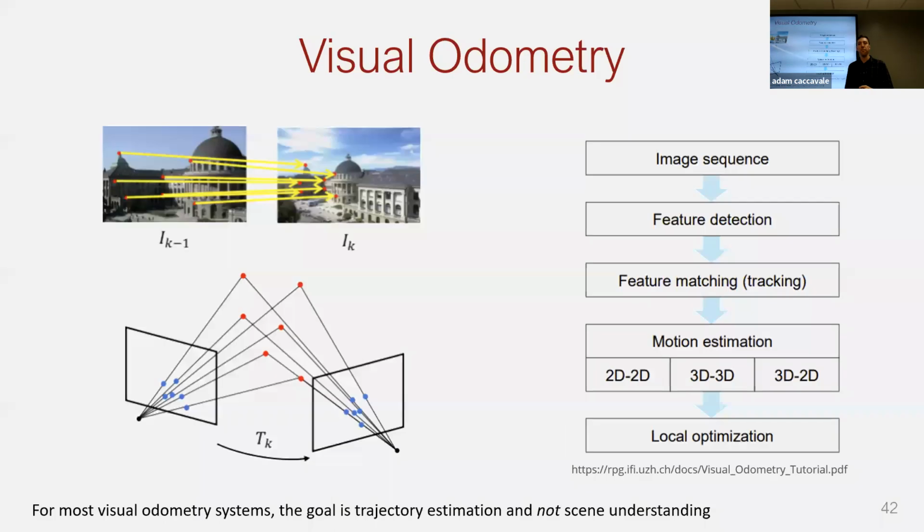object positions. But before I get into my method, I do want to just define the general high-level problem of visual odometry. So this is a classic robotics problem and usually deals with, given two images of the same scene, you want to know how the camera has moved between them based on commonalities. Most typically, you'll scan the image for unique feature points, and you'll try and find which points correspond to the same points in the other image. And based on how these have moved, and geometry, you're able to estimate how the camera has moved.